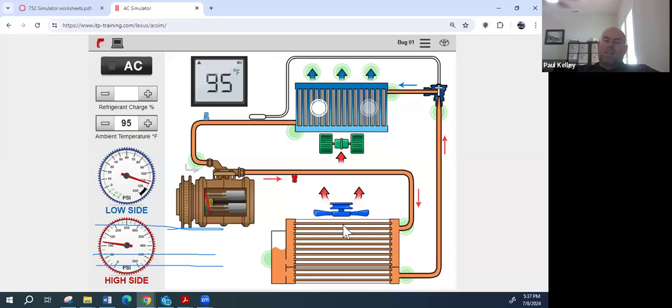Right? First off, the fan's in up, it's not gonna cause the compressor clutch not to work. But if the compressor clutch was operating and it was just a fan, the engine would tend to be overheating, and we could get the temperature thermometer and hit these, and these would be super high, right? So if the temperature is hot, the pressure is high. That's physics. That's the relationship. Temperature is hot, pressure is gonna be high. So we could check the temperature and the pressure, and you know what? They look fine, so we got no reason to think that condenser fan is an issue.